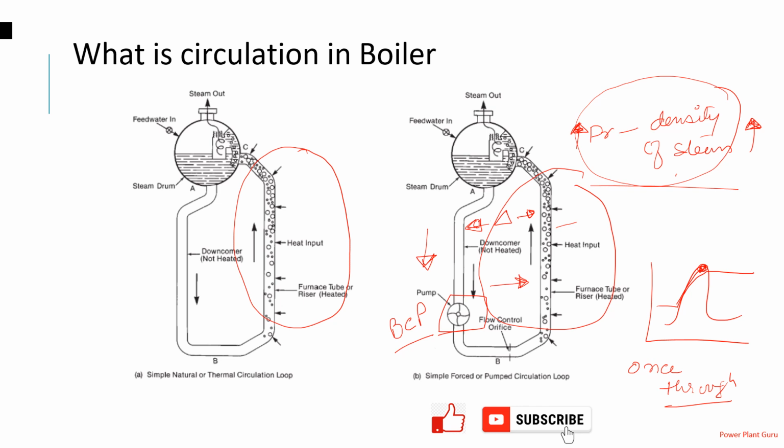Now, I think I have already explained the important concepts regarding this circulation number. And one more important thing to note: as you increase the pressure, the circulation ratio will be low. So that is why at higher pressure you have a BCP, and at even higher pressure you have a once-through boiler. So this is also one relation which you should understand or remember.